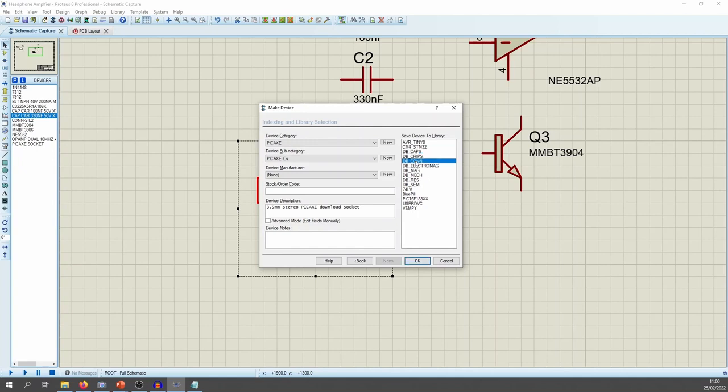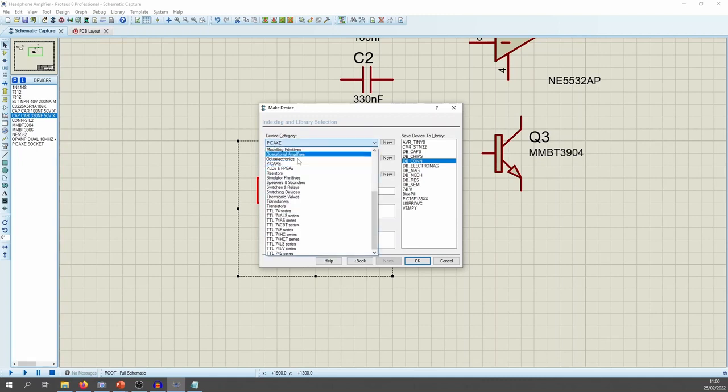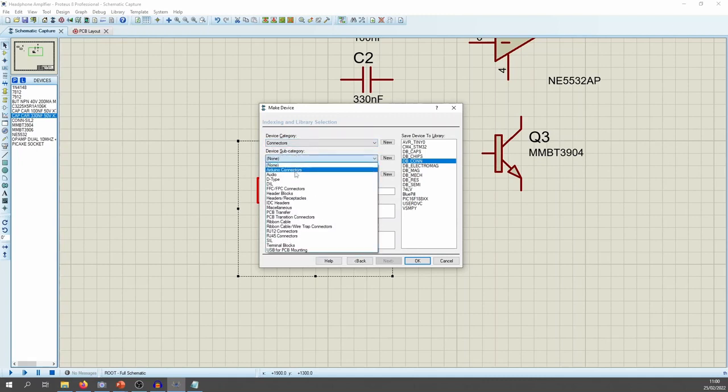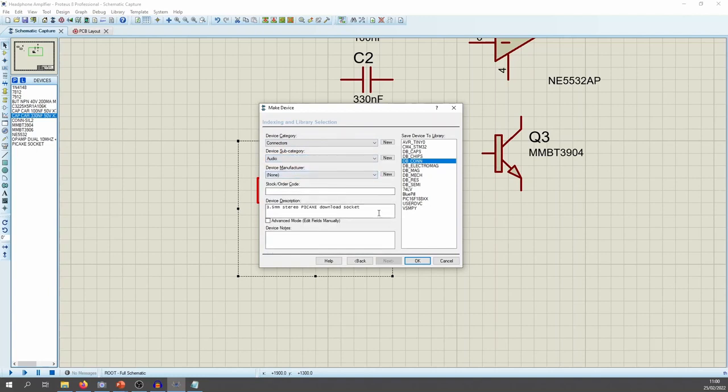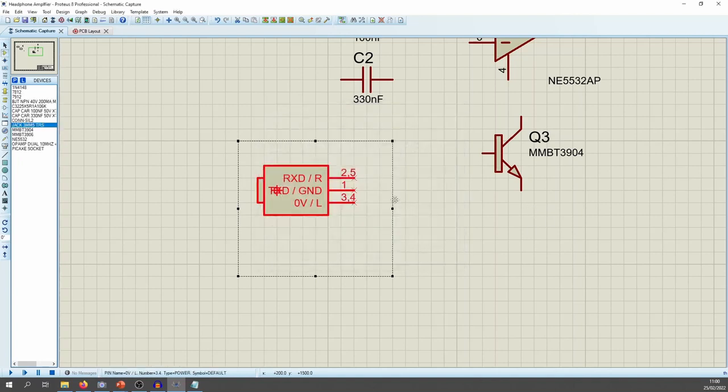Con. Yes. And it's not an IC, is it? It's not that anymore, it's a connector. So it's a connector, and it's an audio connector, so stereo TRS. Let's put TRS in there. Okay, good. Right, nearly done. Connector done. Right, delete this, because this is not even a device anymore.